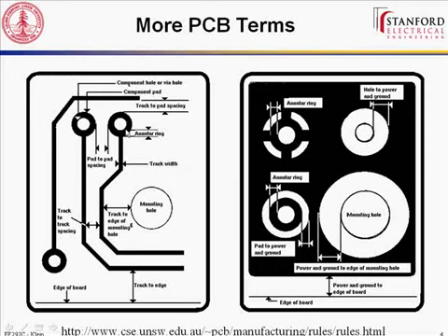So basically, when I put solder on the top, then it will go all the way down. When you put solder on the top, it will wick in, but even if it didn't, it's fine, because the inside wall is plated in copper. The black is copper here, so they make this black trace, they drill the hole, and then they plate the inside of the hole with copper. So there's electrical connectivity even without you soldering. That's how vias work, because vias have no solder inside of them, except whatever is left over from plating.